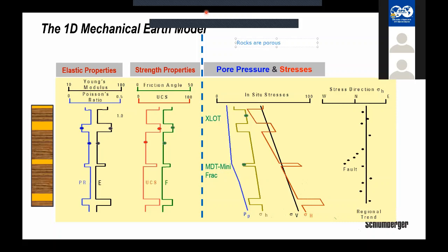Because see, elasticity of rocks can vary a lot. The strength of the rock can vary a lot. At times, rocks can have higher strength in comparison with metals. That is not an issue. That is not a differentiation factor. That will not differentiate rock from metals. The main feature of rocks that differentiates it from metals is its porosity. Okay, now because of this porous nature of rocks, the rocks will have something called pore pressure. Its pores are filled with fluid, and this fluid has some pressure, which we call pore pressure.